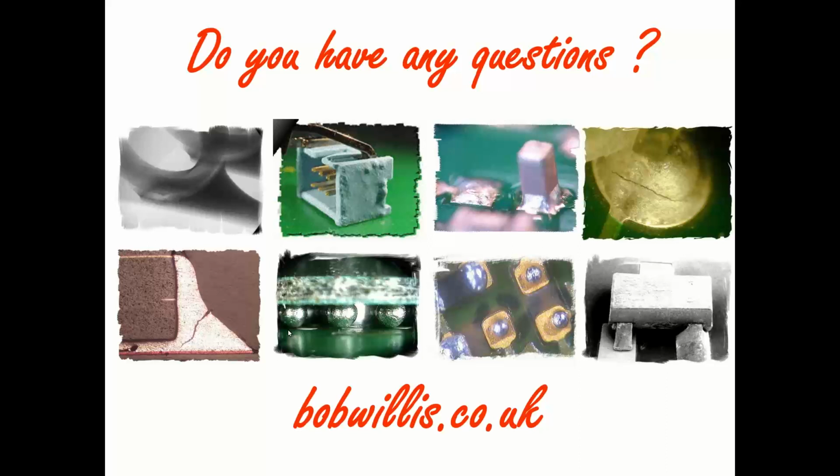Another thing is Zestron, a supplier of cleaning materials, which some of you will be aware of. They have a chemical material they use for testing solder masks and board assemblies. They apply that to the surface and look at the reaction time, which indicates the variation of thickness of that particular mask. That's a corrosion test, but it's really looking at the thickness of the coating. So it's using the technique in a slightly different way.